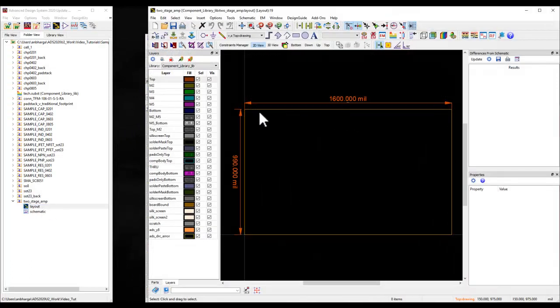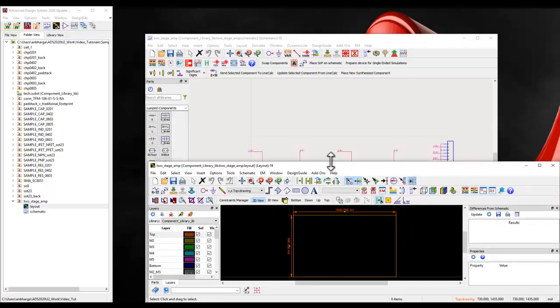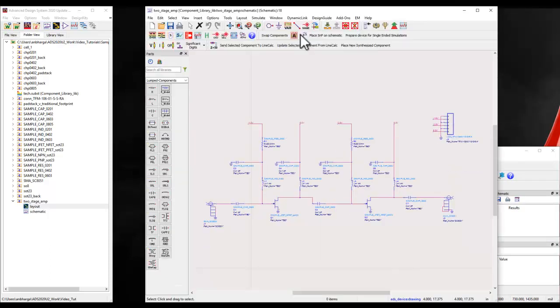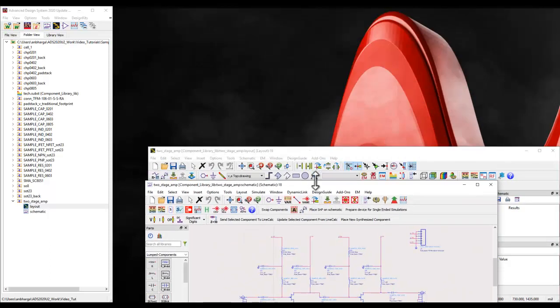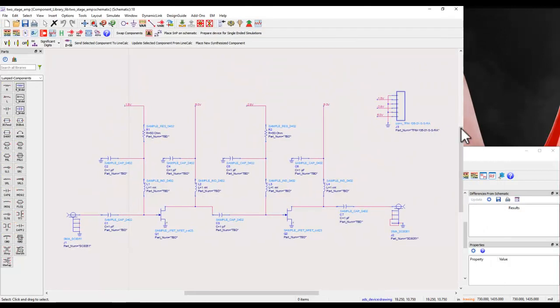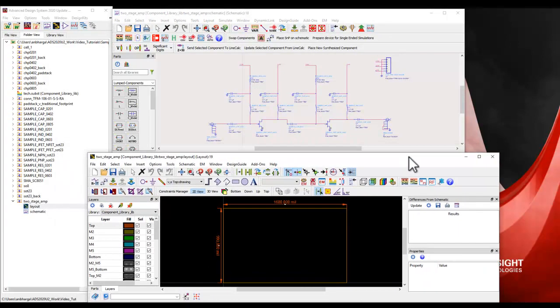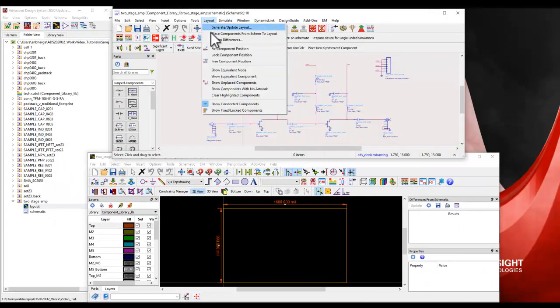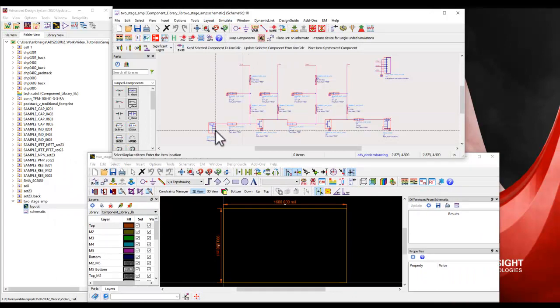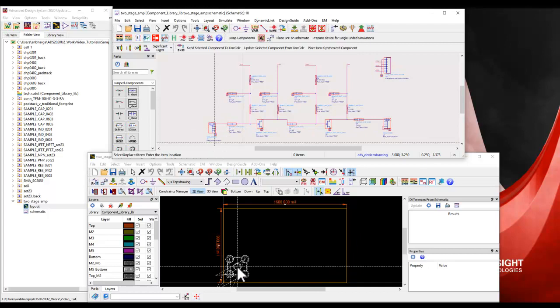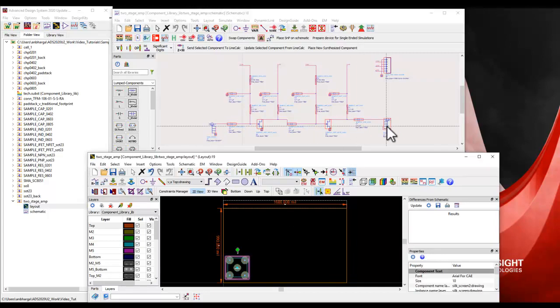Okay, so this is like a layout template, and I want to finish this design into this much of space. Now, using the technique which I just showed you for a sample 3-component placement, I could go ahead and put these windows side by side. And now I can activate that option, place components from a schematic to layout, and I can select this SMA connector. And again, you can decide your source and destination first.